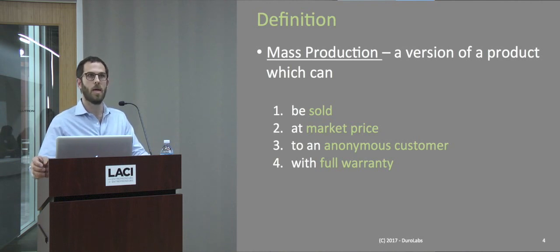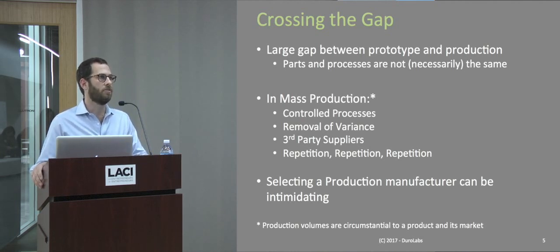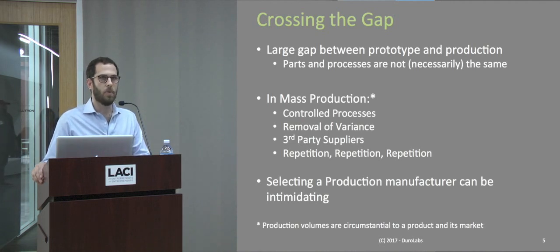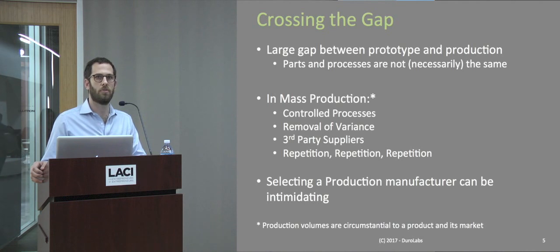prototype. Okay? That's one of the things I want to stress: there's a big difference between a prototype product and a mass production product. And there's a big gap to get from one to the next. It's often undervalued and underestimated, the amount of effort that it can take to go from prototype to production. Many people don't realize that the parts and the processes used to manufacture a mass production product, in fact, could be quite different from the same parts and processes used to do prototyping.